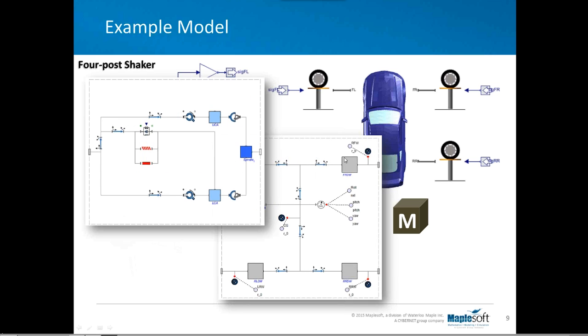And if we look at any of these suspension subsystems, which is a double wishbone type subsystem, we go here and you can see we have revolute joints, and we have universal joints, and more subsystems that represent the mass and inertia and geometry of the upper A arm and the lower arm, and also another subsystem which inside it has more rigid bodies and rigid body frames that represent the mass and inertia of the spindle part. Here we see one of those force components that we saw while we were reviewing the Multibody library, and this is a point-to-point force component, which in this case is used to represent the spring and damper forces for the suspension. And of course there are visualization components to visualize the damper and also the spring around it.